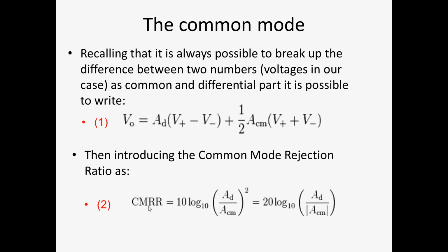So the common mode rejection ratio, we want this extremely high, ideally infinite. It's not the case. Sometimes it's in the order of 70 to 90 dB. If you want to get a sense of how big this number is, just transform it using the relationship, like 90 dB, into a proper number with all the zeros. And I can assure you it's huge. But it's never the case, those aren't perfect.